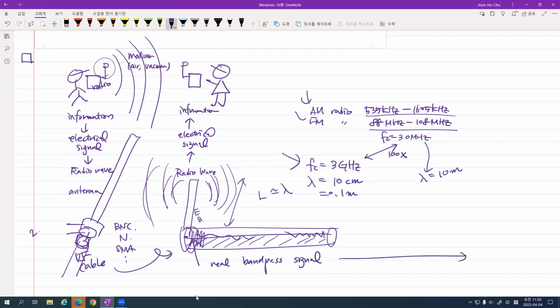So if we use the Fourier transform, what is this signal that is applied to the antenna? It has some conjugate symmetry. Let's say this signal is x of t, and the Fourier transform of it, which is defined as just the inner product between x and a complex sinusoidal function, is what? Since x is real, the continuous time Fourier transform has complex conjugate symmetry.